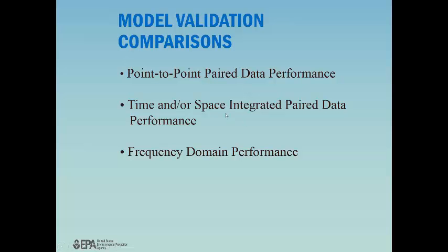We also look at time and space integrated paired data. So you might look at daily values and the total daily flows, or mean daily concentrations and concentrations collected averaged over that day for the values and samples that are taken. So this is time and space integrated, and a little easier comparison to see if you're in the right ballpark or you're getting a good agreement.